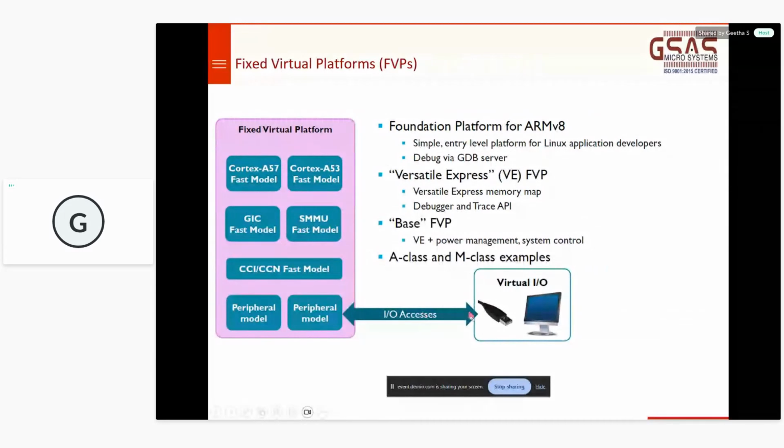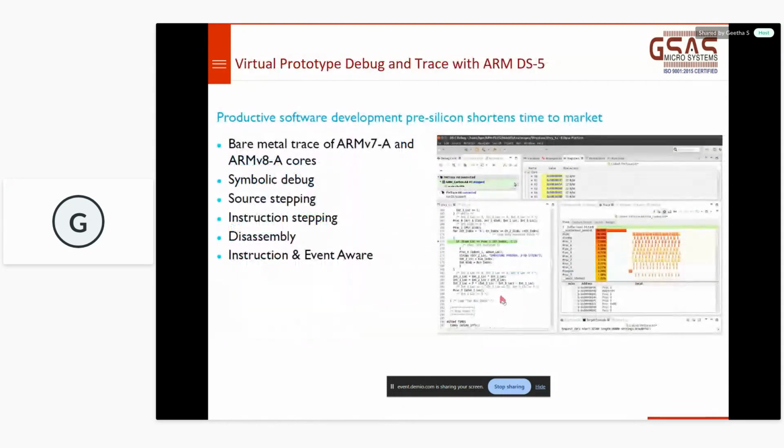For now, just remember whenever you want to simulate any peripheral in your application, like a timer peripheral, UART peripheral, or a DMA peripheral, which can be on chip or external, then we'll be writing the peripheral drivers in our application. Those peripheral drivers in turn will call the registers which are part of these simulation models. And by writing to or reading those registers, the simulation of your application and the models can be achieved. I'll explain that at the end of this slide.